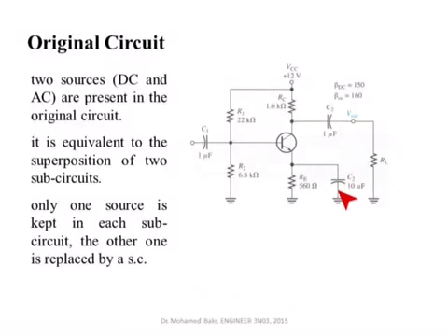and this bypass capacitor to be short circuit. So this bypasses the resistance R_E, completely shorted out. The VCC will be removed and will be equal to 0 in the AC analysis. And then we start to replace the transistor by its small signal equivalent circuit. So we will follow exactly the same mechanism we did earlier. And here you can see beta DC is equal to 150, while beta AC is a little bit higher. But usually they are very close in value, and you will be given these two from the datasheet information of the transistor.